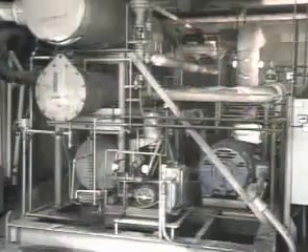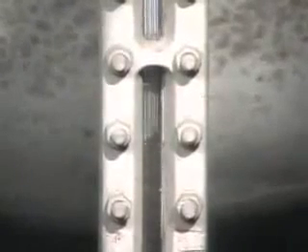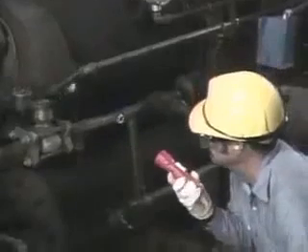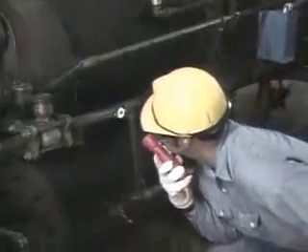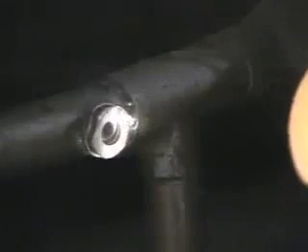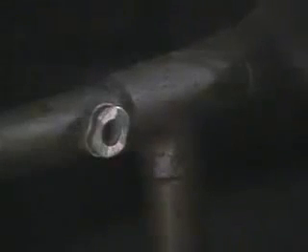One of the more common problems that can affect a refrigeration system is an improper amount of refrigerant. The amount of refrigerant can be determined by checking a level indicator on the receiver or by checking a sight glass on the receiver outlet. When the amount of refrigerant in the system is correct, the refrigerant seen in the sight glass should be clear. If there's not enough refrigerant, the refrigerant may appear cloudy and it may contain bubbles.